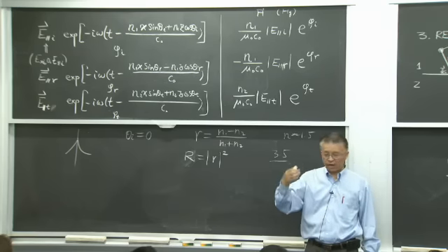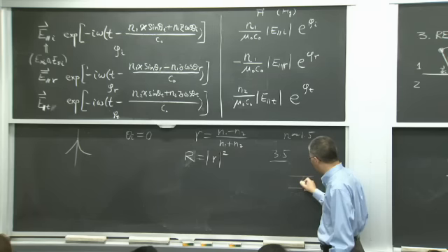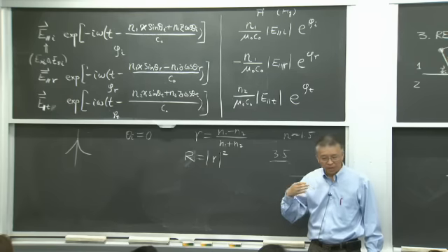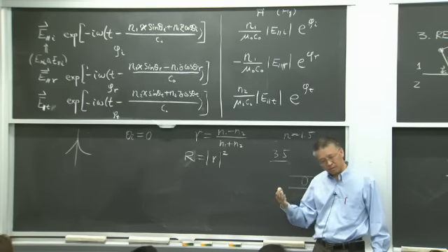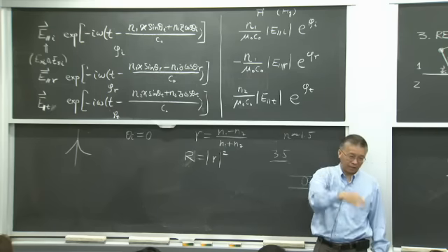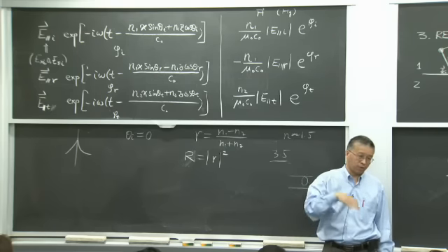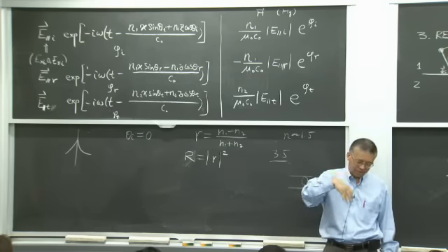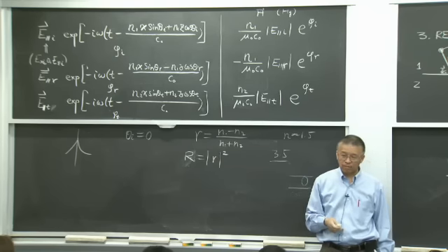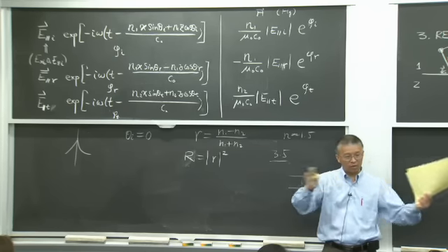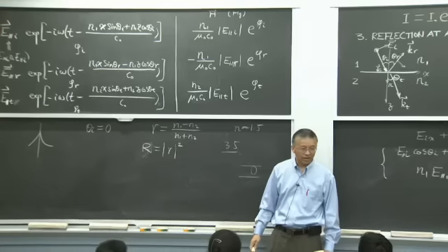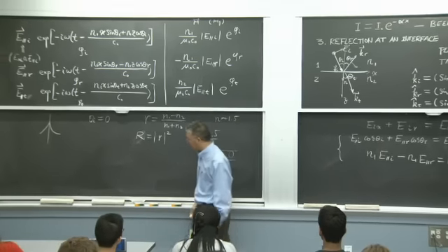If you heat the silicon, if all the light is absorbed, but of course in between the gaps you don't get absorbed, then the emittance of silicon is about 0.7, because the reflection is 30% and the rest gets absorbed. Absorption equals emission. That's Kirchhoff's law. So this gives you now the values that you can appreciate. Okay? We'll continue next lecture.